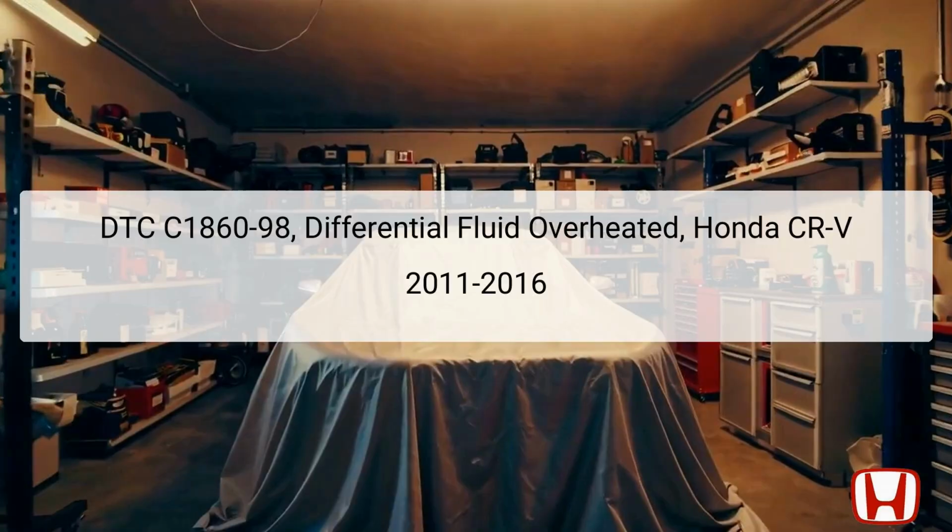The Diagnostic Trouble Code (DTC) C1860-98 indicates that the differential fluid in the all-wheel drive (AWD) system has overheated. This code typically activates when the clutch, a crucial component of the all-wheel drive system, is suspected to have reached a high temperature. The system safeguards itself by disengaging the clutch engagement to prevent damage.